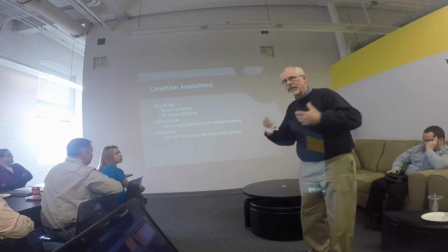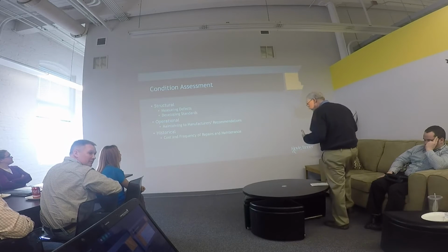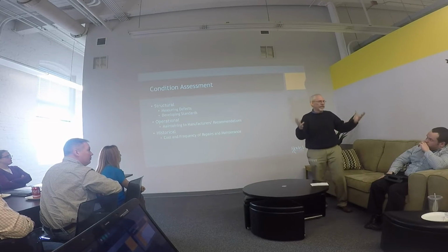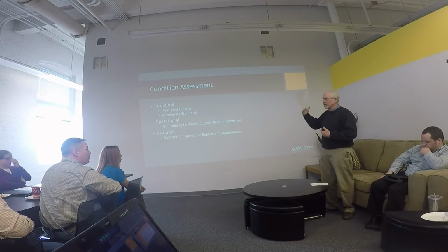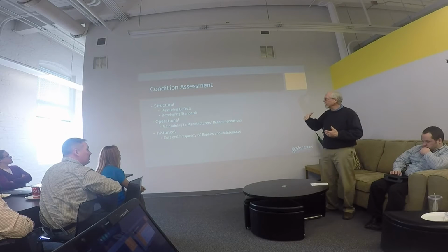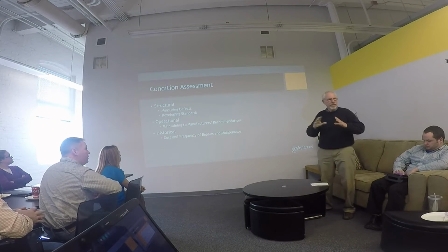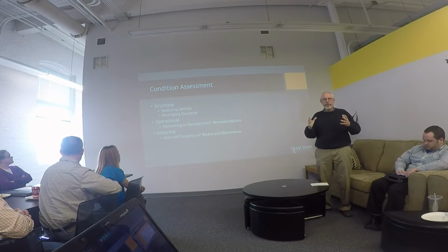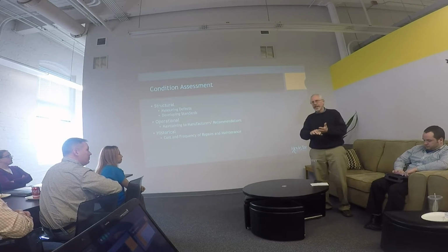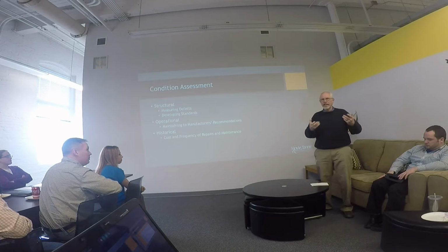Okay, we're going to start off with condition assessment. And condition assessment, you use it in every single one of the disciplines that we have here. And condition is developing a standardization. So if you look at something structurally, you have to see what defects you are measuring on that. If it's a pavement, you're looking at cracks, sags, rutting, and everything else.